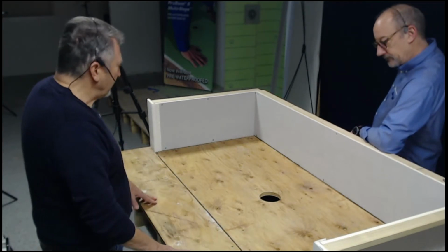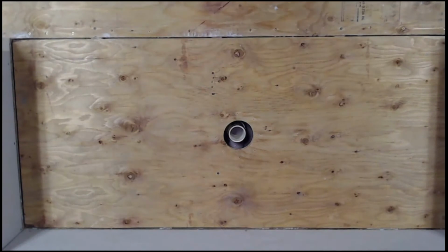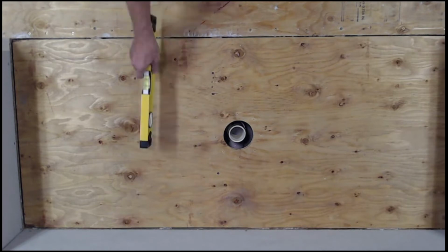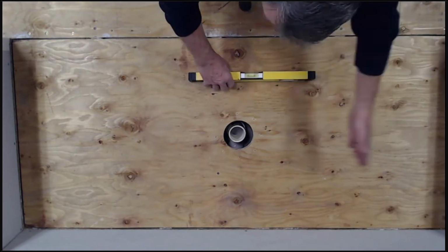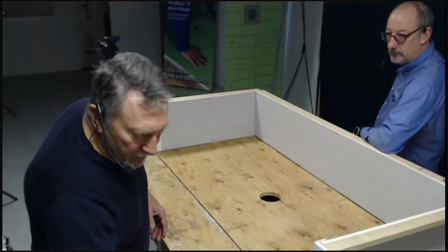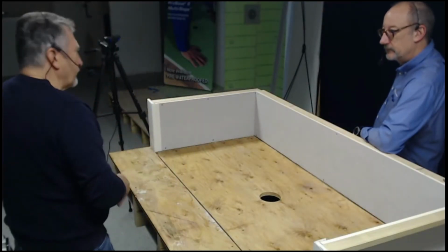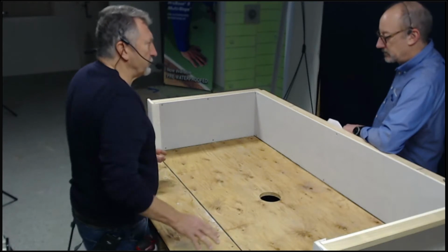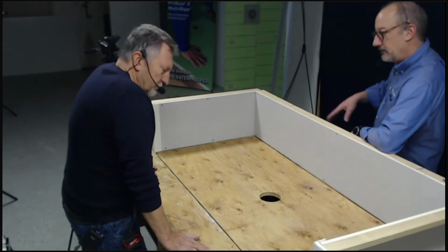Okay. As you can see, my wood frame construction, first of all, I'm going to check to make sure that my substrate is flat and level. Just put your level on it, straight edge, make sure that you're flat. If not, you'll have to fix it by using, say, leveling compounds. Much like installing a bathtub or anything else, it's got to be flat. Yep.